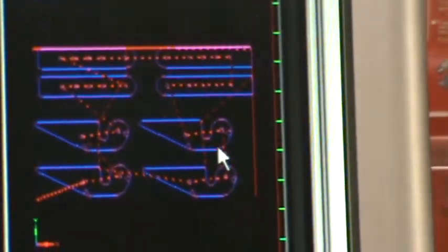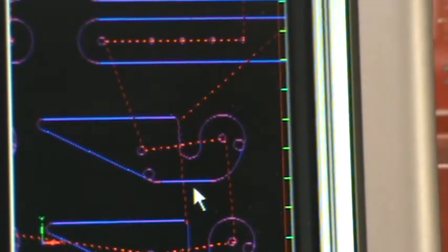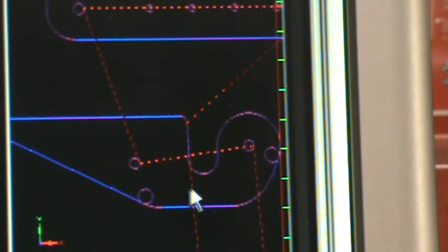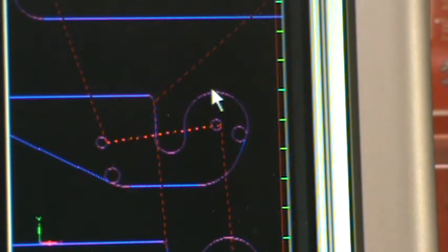Oops, zoomed in just a little bit too far. So you can see everything looks pretty good, but you see these little pink circles? These are what I'm referring to as crop circles. Now these things are just a major pain in the butt because you'll see that the pink comes in, this is a cutting part, then it does a 360, and then it comes back and it starts cutting, and it does that, and it's cutting some more, and then it does another 360, and that's it.